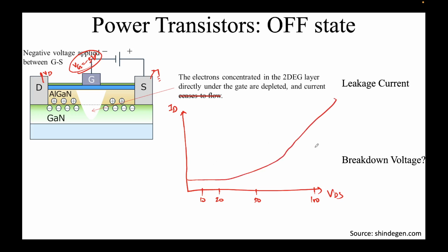Okay, and this is the threshold line. When the current crosses this value, we'll say the device is broken down. And we saw, I'm using the same numbers, 10 microamps per mm, and correspondingly this came out to be 75 volts. I'm only drawing ID here, just to keep things simple, but if you recall, it was ID plus IG rather. Okay, so this is the drain current that we have. So 75 volts is the breakdown voltage for this particular device, and I'm not going to repeat myself again, because we have talked about the 3-terminal breakdown in great detail. Okay. This is the compliance level.